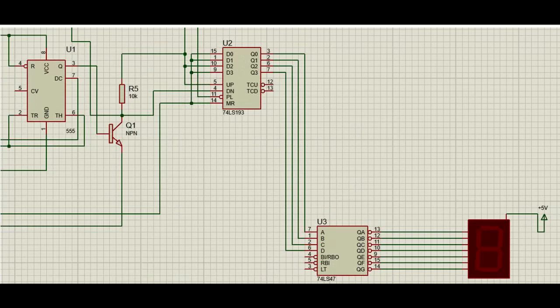The components used here are the 74193 BCD decade counter, up or down, and the 7447 7-segment common anode decoder. As previously mentioned, we have designed our 555 timer to output pulses at 1 second intervals, so we can easily and accurately display the remaining time in seconds with a down counter. We are using the 74LS193 IC.